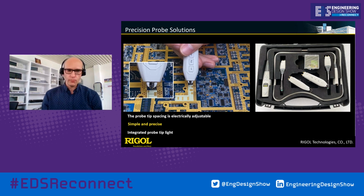And the probe head you can see here on the picture has an automatic knob to set automatically the distance. And with the buttons 1, 2, 3, you can store in the internal memory 3 different distances, which come quite often. And so you don't need to adjust everything in the beginning. You can store them, and then you can select 1 for one distance, 2 for another distance, and 3 for the third distance. And you have also the possibility to activate the light at the front tip, to have more view at your PCB board.